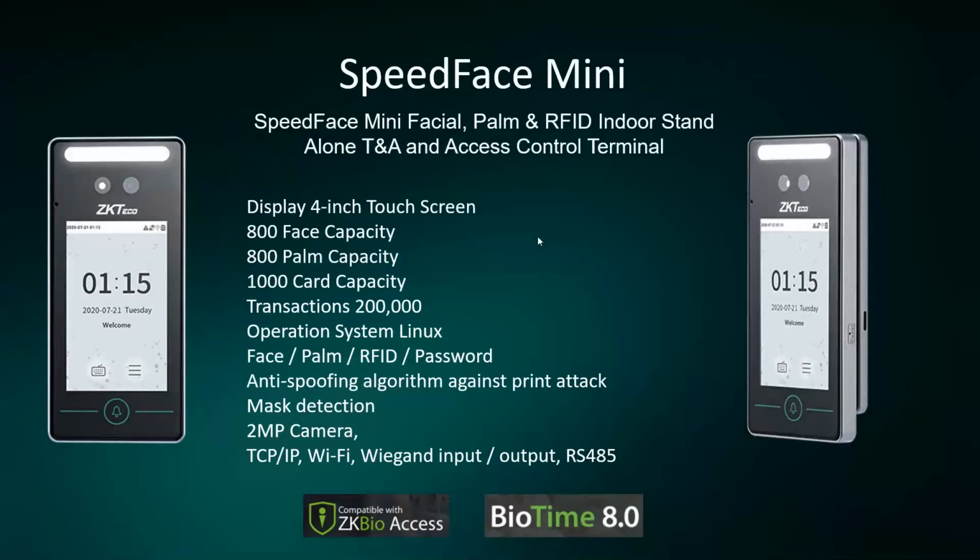So you can convert this device into either an access control device or a time and attendance device. Not both, because that's going to make it a bit difficult for your access control side of things. Always remember to keep your access control solutions apart from your time and attendance solutions, because your access control solutions are going to be spread out through the entire building. You don't want time and attendance solutions throughout the entire building because that's going to make the reporting structure a bit more difficult, because it's going to keep on saying that this employee clocked in and clocked out, clocked in and clocked out at each door.